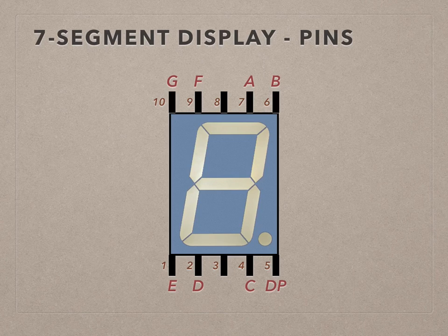The 2 center pins on each end are either a common cathode connection or a common anode connection, depending on which model of the display you get. The FND500 is a common cathode model, which means that the pins 3 and 8 are both connected to ground, or the negative terminal. The FND507 would provide a common anode connection, meaning that these 2 pins would be connected to the power supply, or positive terminal, and the segments therefore connected to ground.